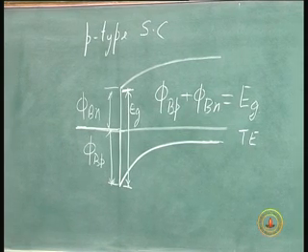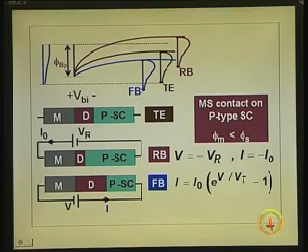In this particular case, what I have shown is the phi BP here, then the thermal equilibrium by this curve, and this distribution is the distribution of holes. Just like you have electrons in the conduction band above the conduction band up to a certain level, the same, similar distribution is there for the holes in the valence band. I can talk of absence of electrons similarly in the case of metal here, though people do not appreciate if you say holes in metals. What holes are there? There are not real holes there, okay? There is absence of electrons.